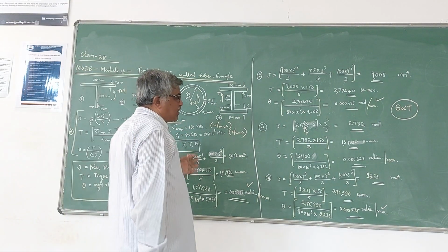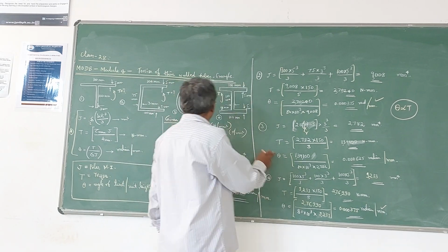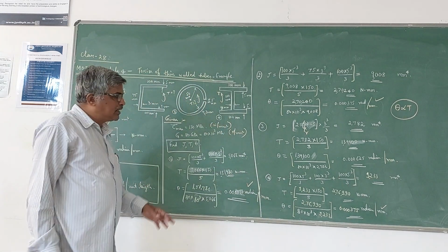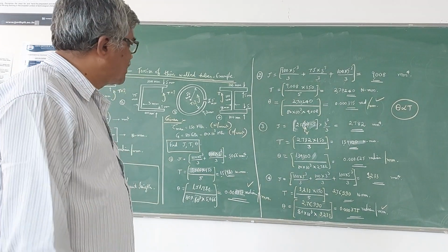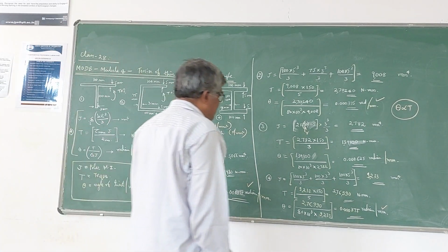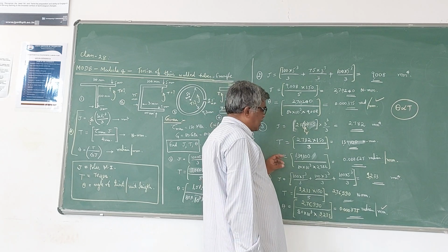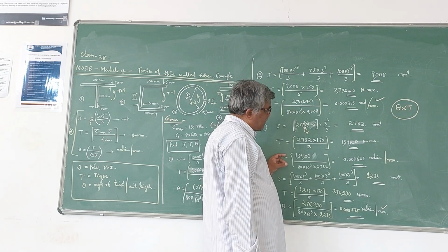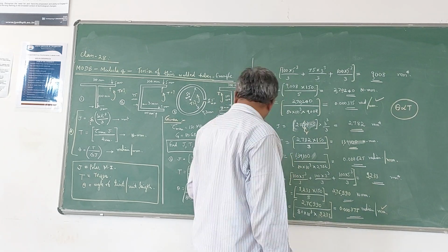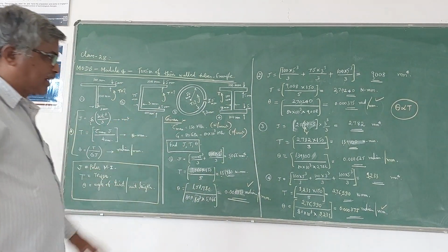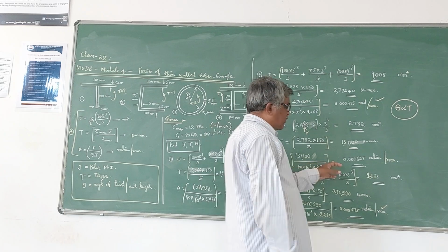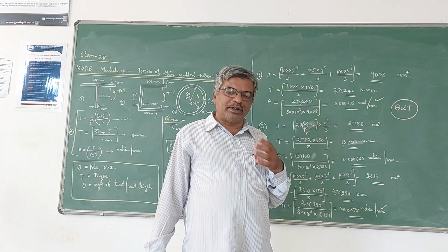In this example, the third section, the circular type with the gap, is giving a lesser torsion carrying capacity, or rather a lower angular stiffness, and it is twisted more. So this is what I wanted to explain.